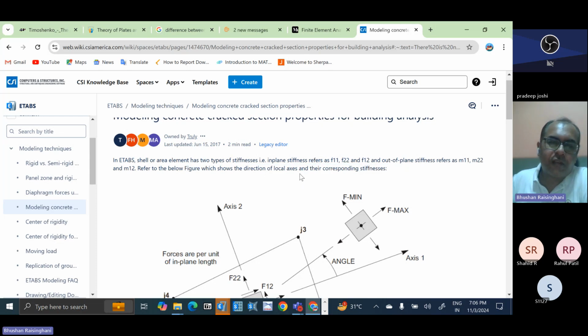Okay. So we are actually doing the in plane stiffness parameter and the out of plane stiffness parameter. In plane is given by F11, which is direction 1. As I had mentioned, that is sigma x. At that time, you had seen that there was some xy subscript. So force is in the one direction. This is the normal axis.